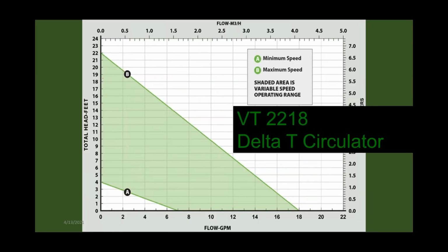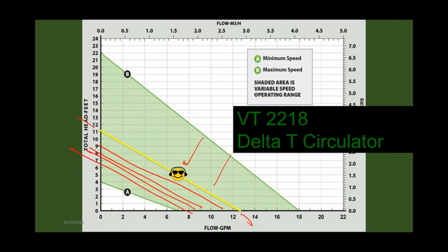So I'm really not taking full advantage of this really cool piece of technology. Delta T gets a little easier as well. 7 gallons a minute at 5 foot head. By golly, this is where it's going to work. And as zones close, the performance curve is going to shift to meet the requirements of the system, and that is unique among variable speed circulators. In this case, as zones close, the performance curve is going to drop and drop until we're down, maybe where my smallest zone is under design conditions. I'm going to work here, and as zones open, I'm going to work up here at a higher speed. At some point, I'm going to have a fixed speed 9-watt pump, and my delta T won't be 20, but it's not going to be 5 either, or less than 5.